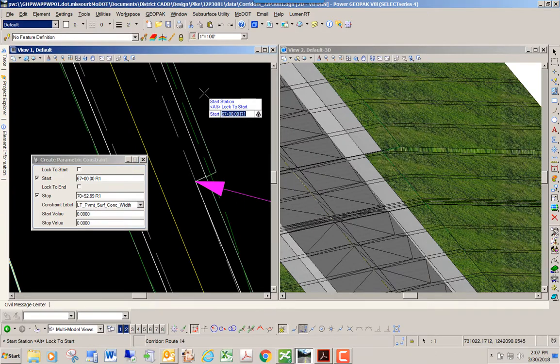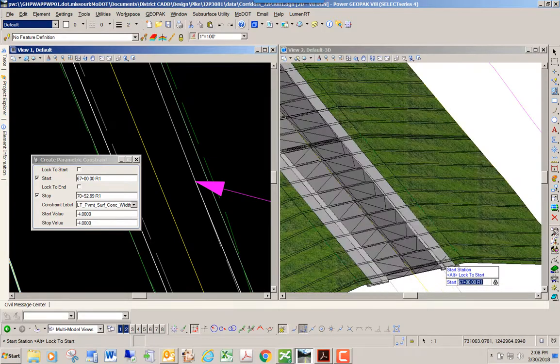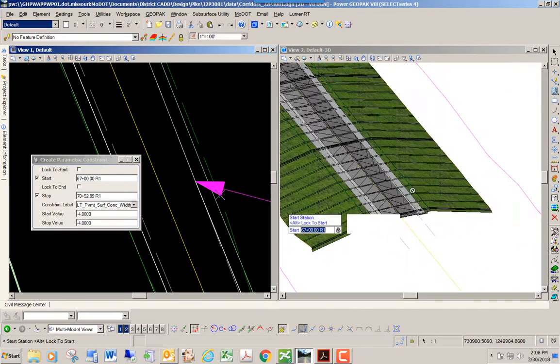And so I got the whole dialog filled out, and what we should see is when I just go through and accept all these values, you should see that again, that widening go away and that shoulder just butt up just perfectly well with the other one. So I'm just going to start accepting with left clicks. And boom, that's what we wanted to do. Okay, so we have no widening in this area, and we have a little bit of widening. It gets wider and wider and wider until it gets down to this location here.